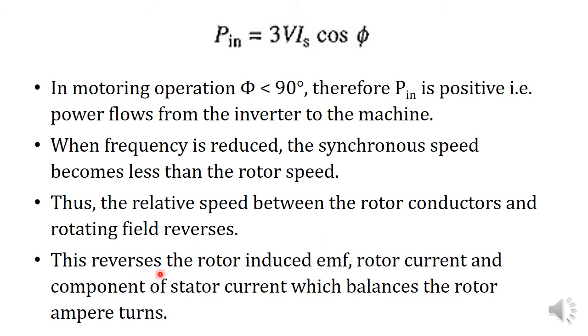So the rotor induced EMF, obviously the rotor current, and the component of stator current which balances the rotor ampere turns, all reverse. That means a component of IS will become negative.